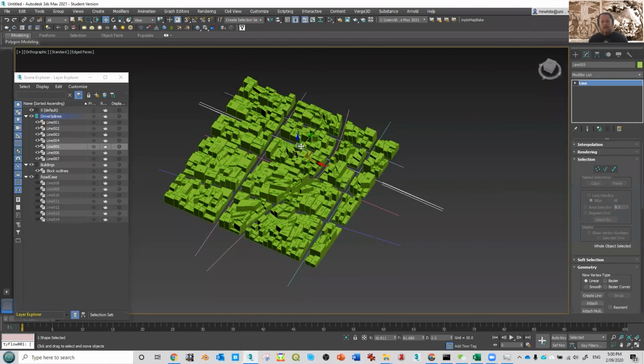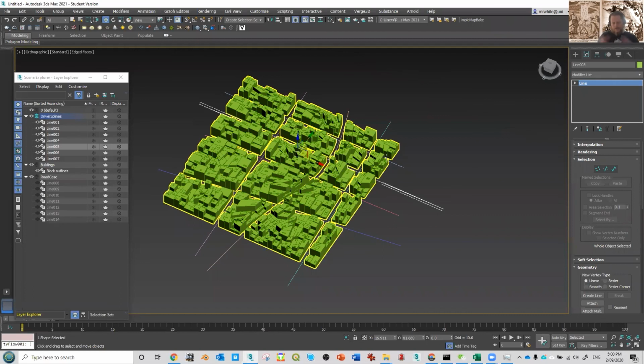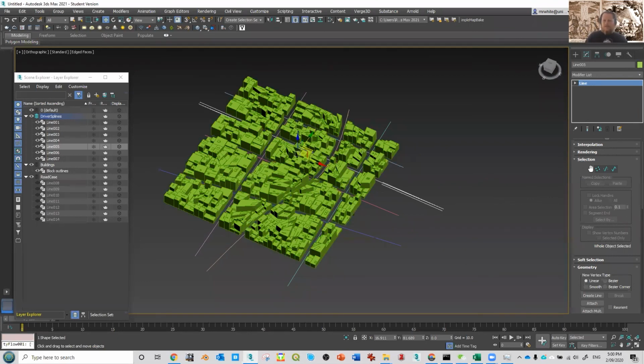Now, if I move this spline, it's not going to do anything, because I can move an instance copy independent of another instance copy. In terms of spatial location they're not linked, but they are linked in terms of their actual geometry and their sub-object.